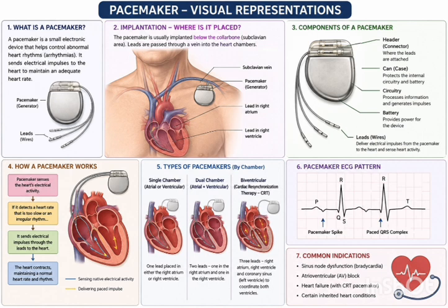The pacemaker continuously senses the heart rhythm. If the heart beats normally, the pacemaker remains inactive. If the heartbeat becomes slower than the programmed value, the sensing circuit detects it first. Then the control circuit activates the pulse generator. The pulse generator sends a low energy electrical pulse through the leads. The myocardium starts to contract. The heart pumps blood normally.